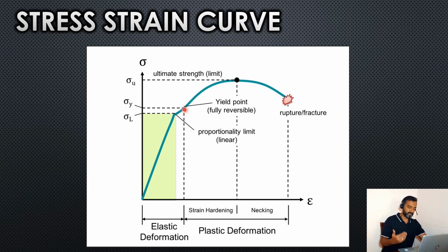If you put X amount of force, and the force is not beyond this point, it will not deform. But if the force goes beyond this point, it will deform. That is where it exceeds the minimum capacity of the material. This is what we term as allowable as per ASME B31.3.